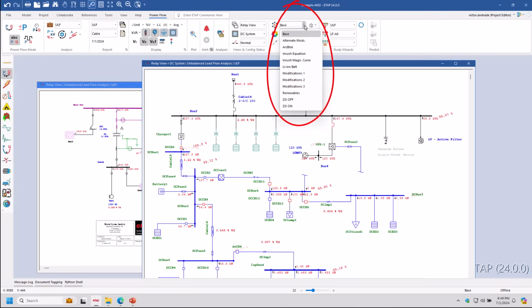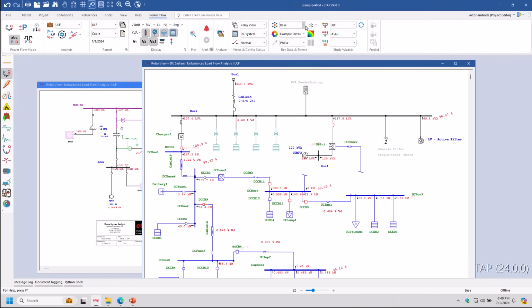So the data revision is when you're doing planning for the future, or you're trying to do arc flash mitigation or a protection coordination study. This gives you the ability to change protected device settings or any type of system data without making changes to the base, correct? So the base is understood to be how the facility is constructed or how it is currently operating right now. You then have your color contour, and then finally you have your scenarios, right?